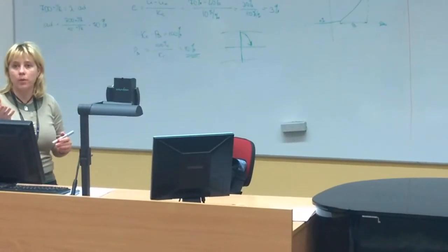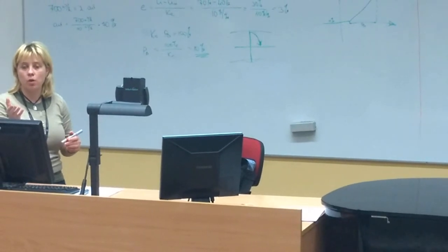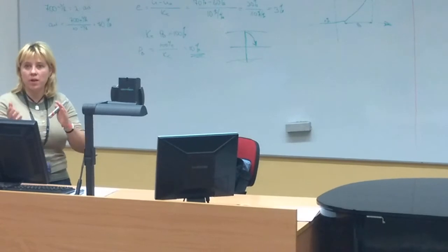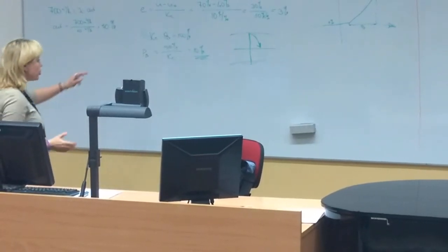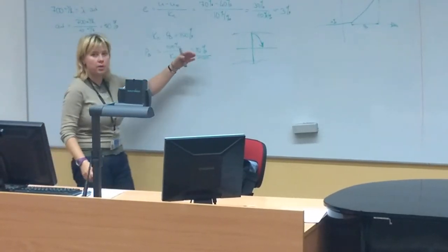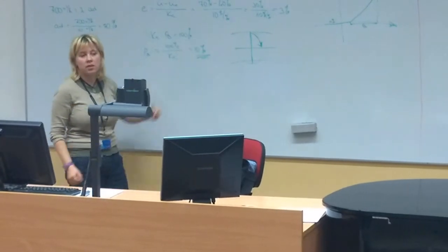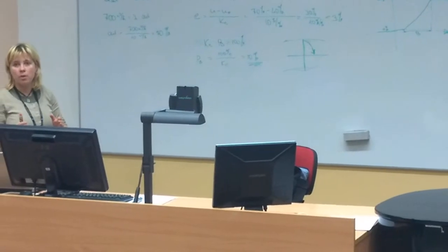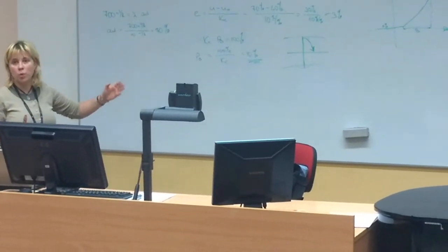If, for example, we talk about our laboratory works, then we deal with temperature. So there we have different types of controllers. In some controllers, we should set a proportional band in percent. And in other controllers, we should set our proportional band in the units which we are using.